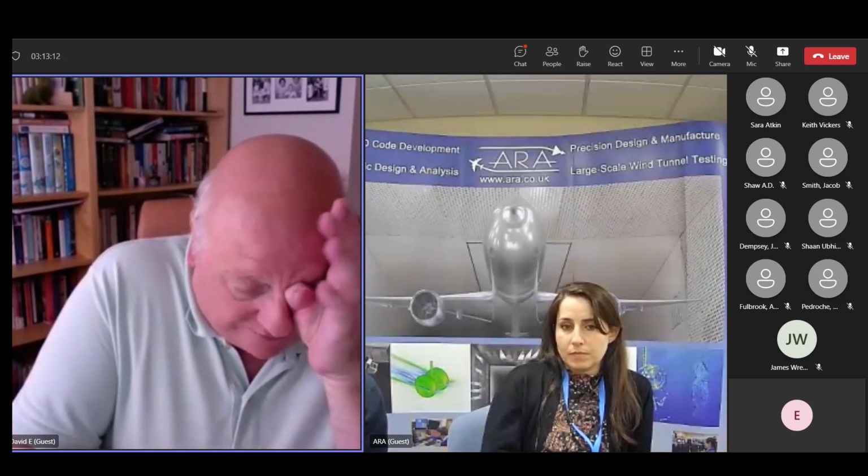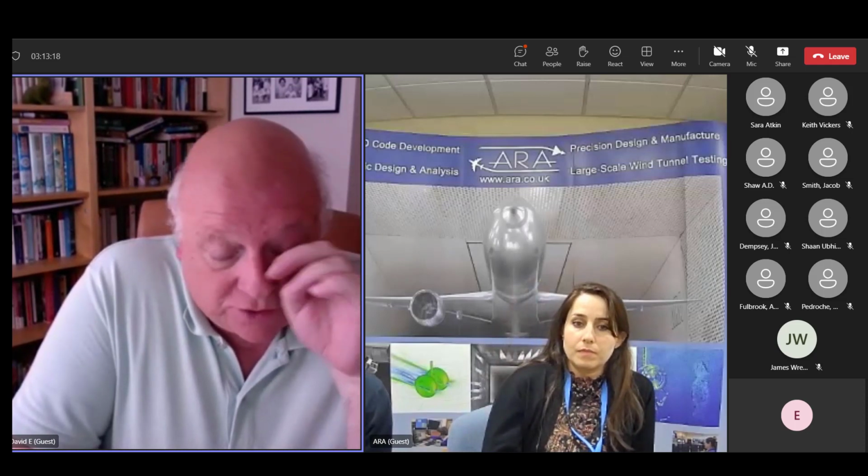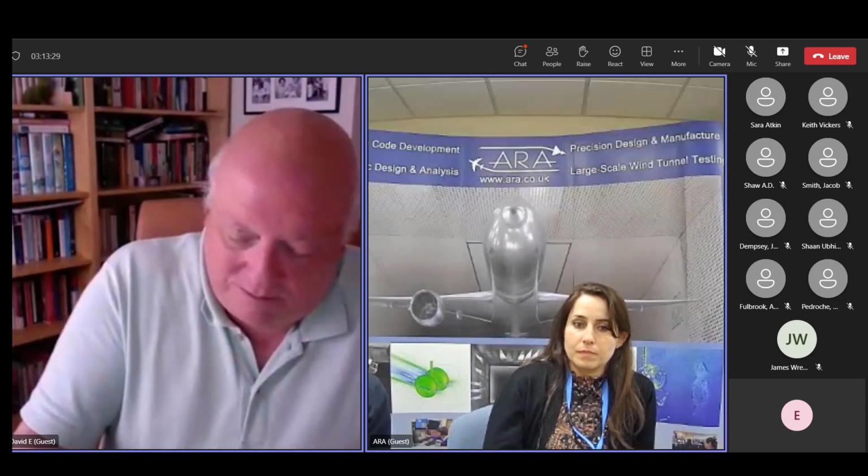Yeah, so my suggestion about photoelasticity with the plastics is for deciding on where you put strain gauges and the orientation, and optimizing orientation. Photoelasticity is not something you can do on anything that's actually got that much thermal change. Right, okay. But it's a very good technique from quite a few years ago. It's a good whole device visualization.